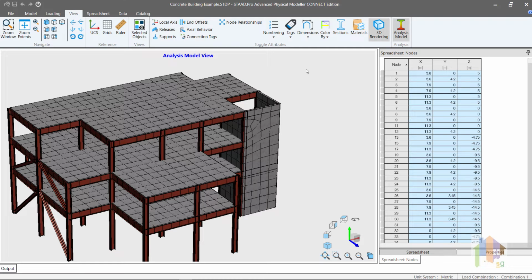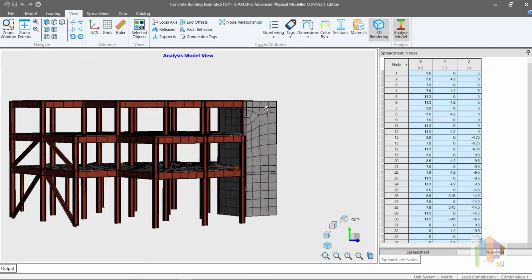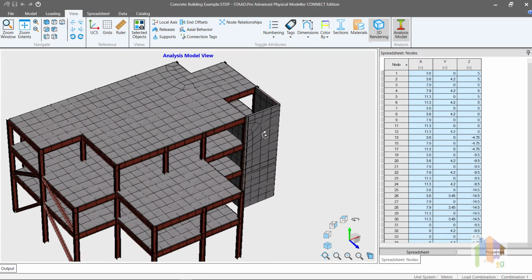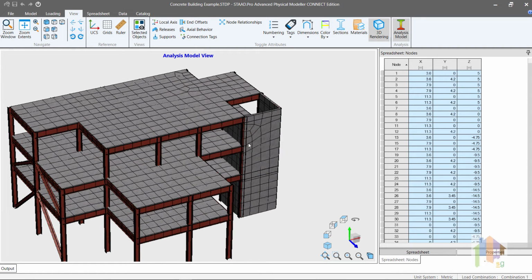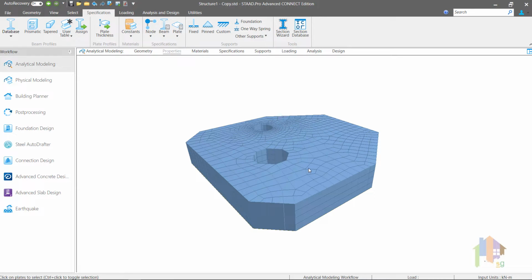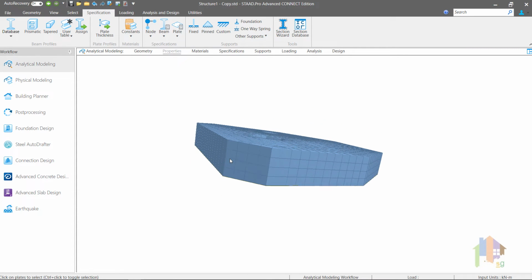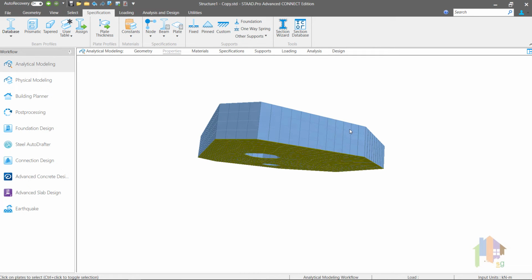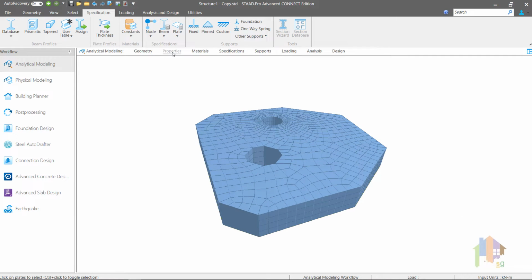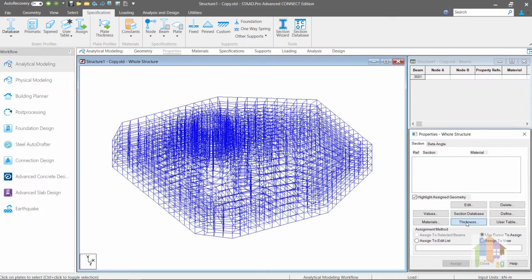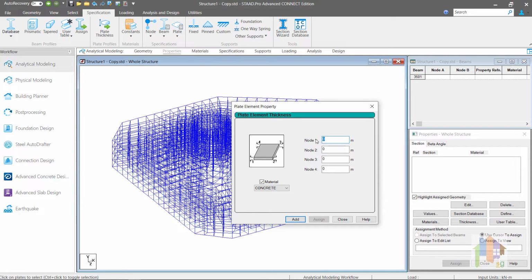For a shear wall or floor diaphragm, thickness is normally very small compared to the other dimensions. So we can easily model it using finite element meshing. But for a machine foundation or a dam structure, thickness is comparatively very high, from just a meter to several meters in a few cases. If you try to model it using plates, then you have to assign plate thickness as 1 or 2 meters, which does not produce satisfactory results.